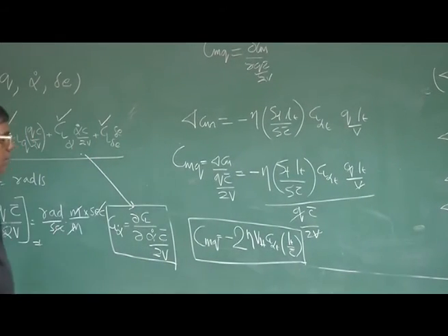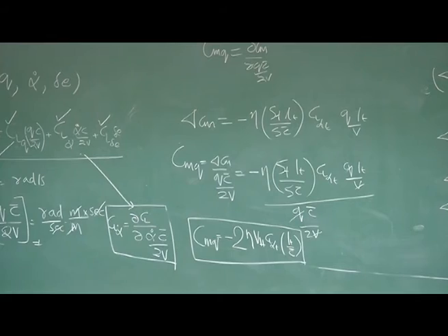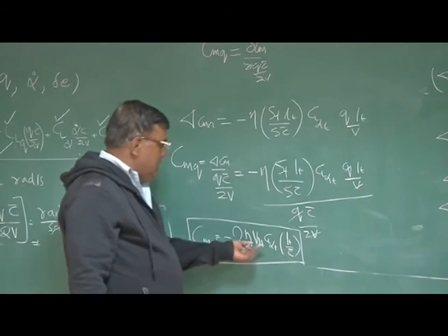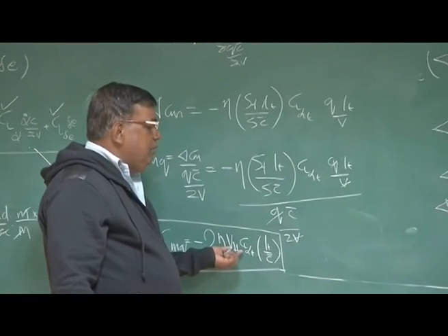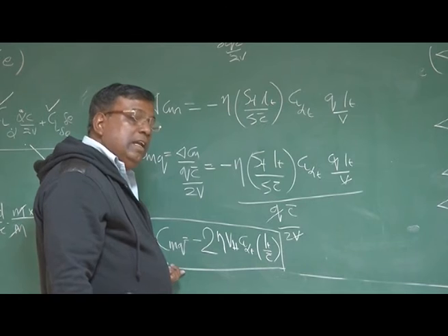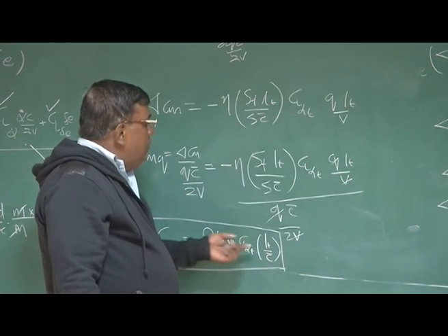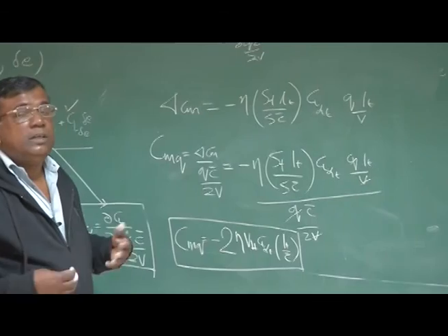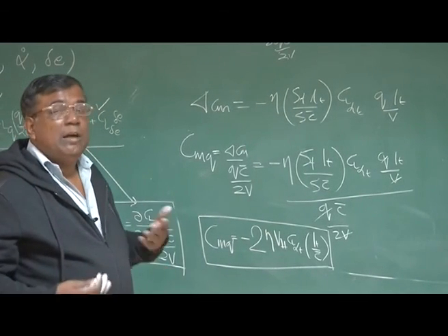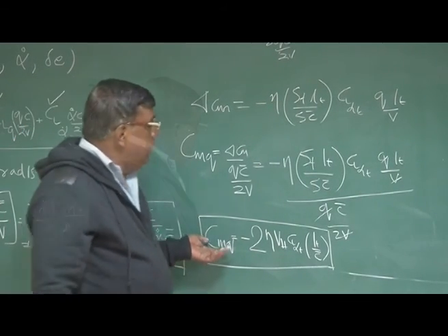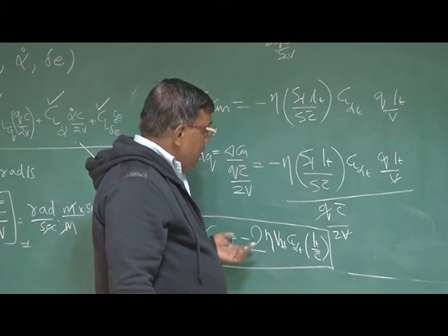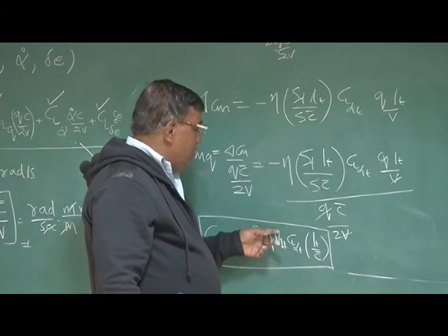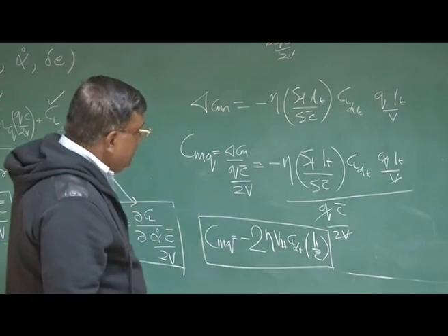You could see one thing very interestingly, that if we change L_T, if we change V_H, that means if you are changing V_H, C_mq is largely affected. And also if you change L_T, this also will change C_mq. Suppose you want to increase C_mq. C_mq means what? Damping. No? So this will tell you that if I want to increase damping, increase L_T or increase V_H or both. Okay? This is extremely important.